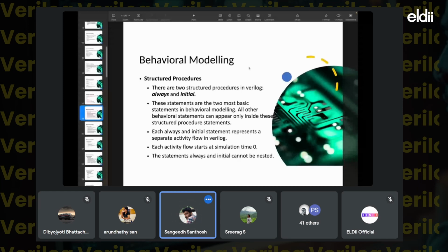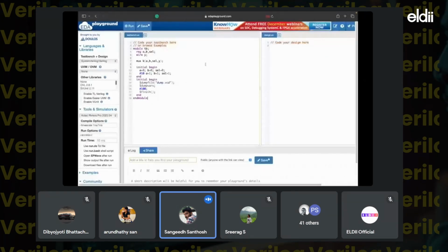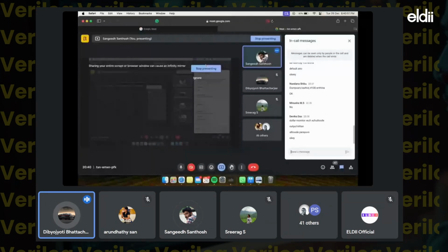Because all of these examples I have given are combinational circuits, right? That is combinational and sequential circuits. Sequential is a circuit where the current state depends upon the past state, and in combinational you get a set of inputs which produce a particular output, like the half adder. So for a sequential circuit we need a memory. Yes, it depends on the previous state for an output. In combinational, you get a set of inputs to get an output.